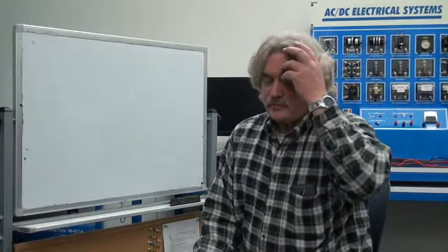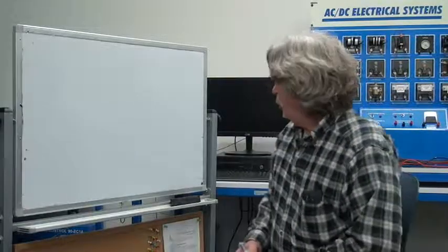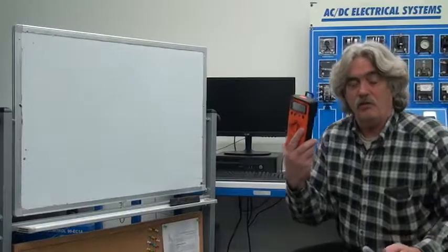And what they're having you do in Learning Activity Packet 2 is measure voltages and current. And you have to have a good understanding of what voltage and current is. And so there's a lot of analogies you can do when you're describing electronic circuits or electrical circuits. And the problem is you can't see electricity. If we taught this with hydraulics or pneumatics or any other medium, you could see pressure and flow rates and all that kind of stuff. But when you're dealing with electronics, if something's got 20 volts, you can't tell by looking at it. You have to trust the numbers that are on your voltmeter.